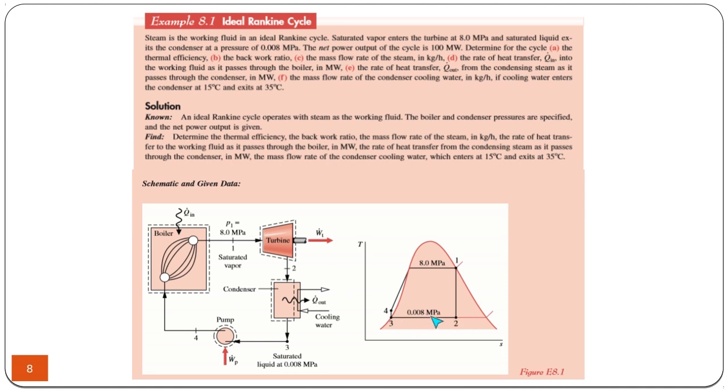It's a vacuum pressure, less than atmospheric pressure. We need to have less than atmospheric pressure because when the pressure is low, remember that the saturation temperature is also low. So we can have a saturation at a much lower temperature if the pressure is also low.